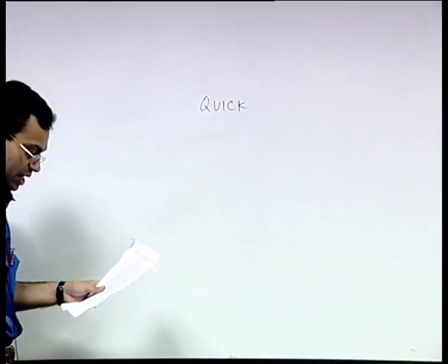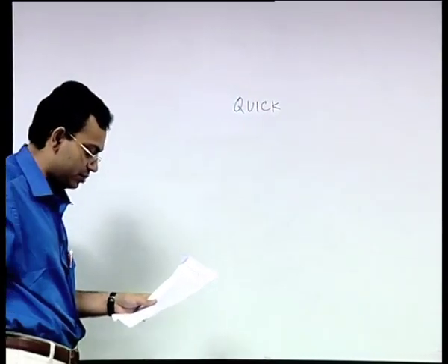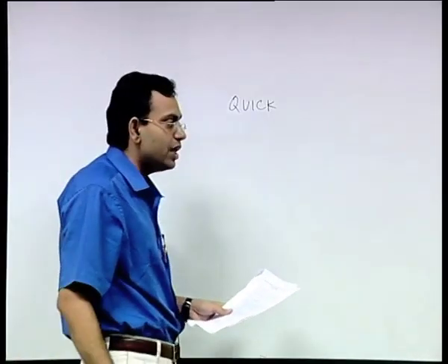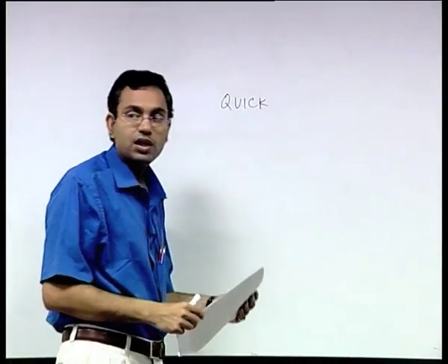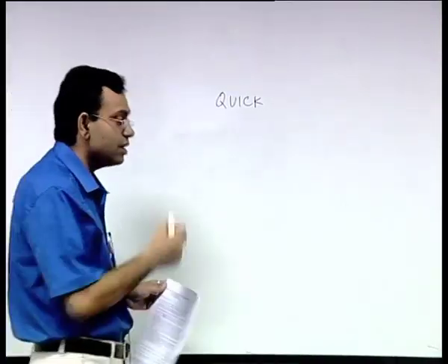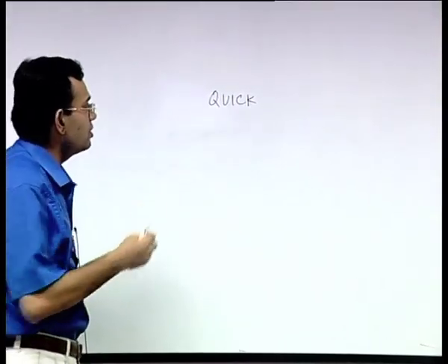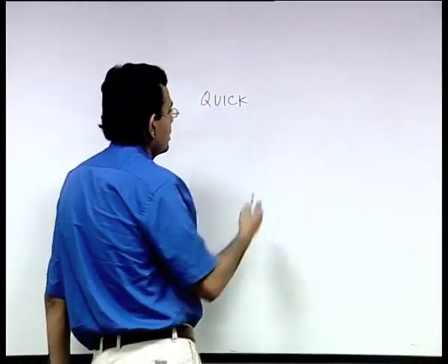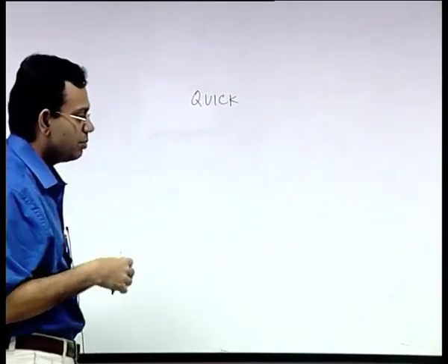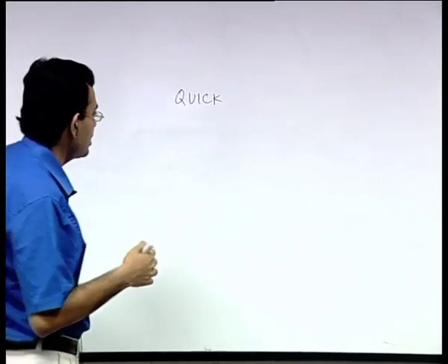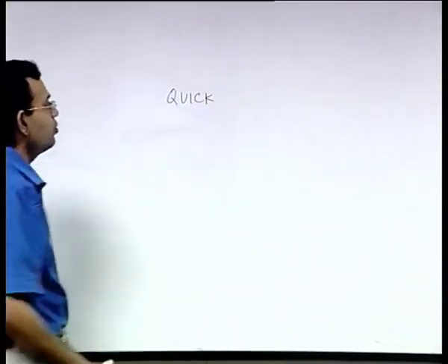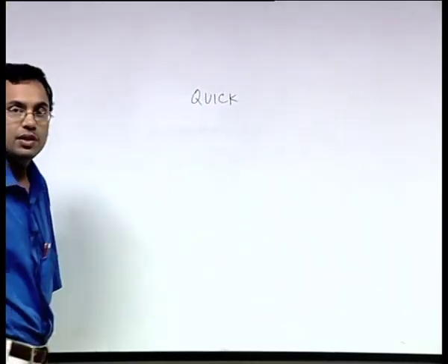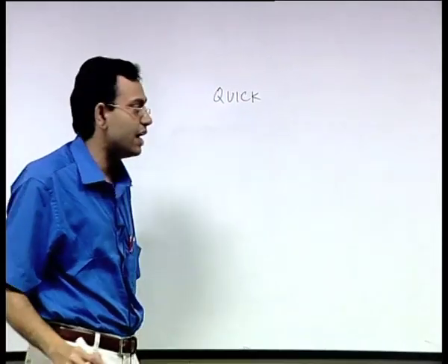And considering the same profile assumption for the diffusion term, derive the complete discretization equation for the convection diffusion problem. That is the first part. So, this we have done in one of our previous lectures. Just to summarize, the QUICK scheme refers to the quadratic upstream interpolation scheme for convective kinetics.